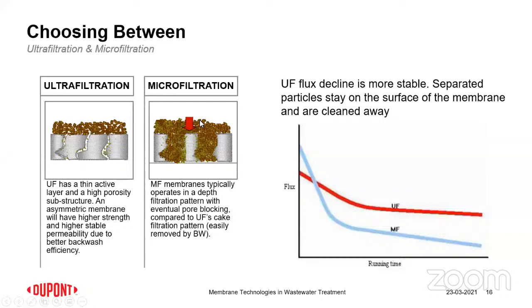Usually, it was a combination of depth-based filtration and membrane-based filtration. You'd see filtration occurs by the membrane along with some level of cake layer filtration. So when you do a cleaning, the passage of pollutants is much easier in the case of MF. In the case of UF, irrespective of feed quality, it's not dependent on the cake layer for filtration. The cake layer can make it much better than your expected filtered quality, but the minimum filtered quality is always assured in the case of UF.